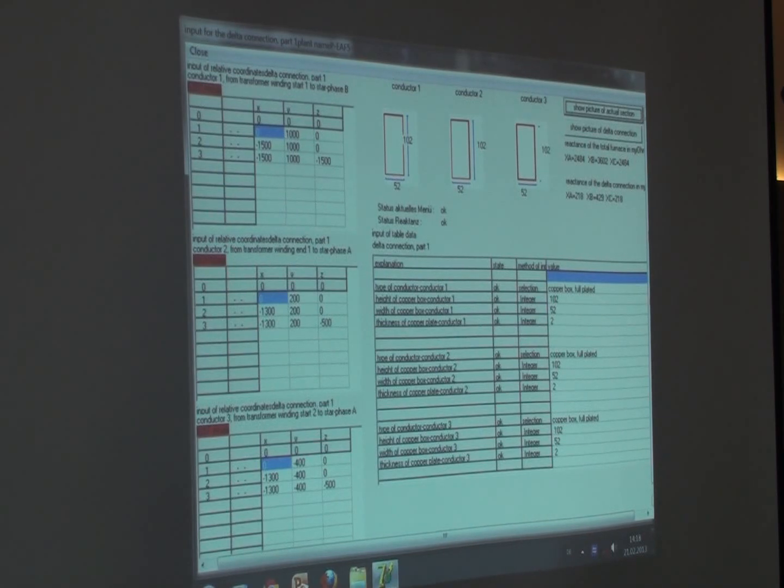It is possible to construct an additional reactor for reactance symmetry on the delta part. This we did make. The result would be unsymmetrical reactances on the delta part. The voltage drops at the closed loop would not be equal, and there will flow an additional loop current. This current can destroy the secondary winding of the transformer. This I have shown you now.